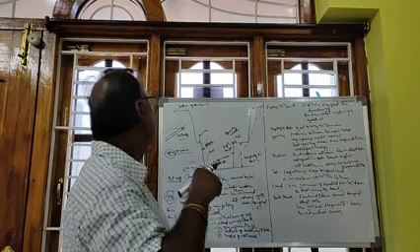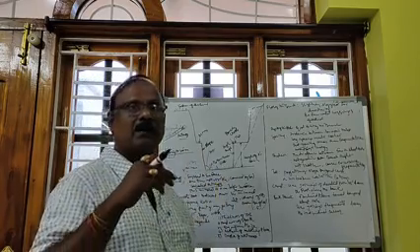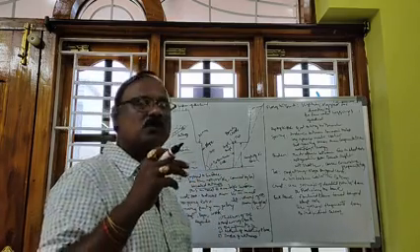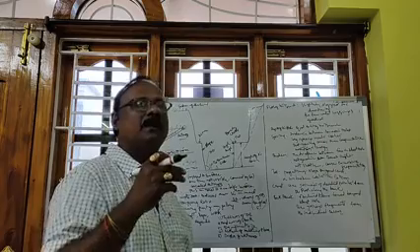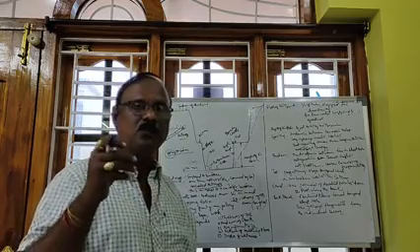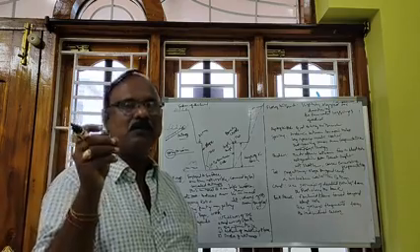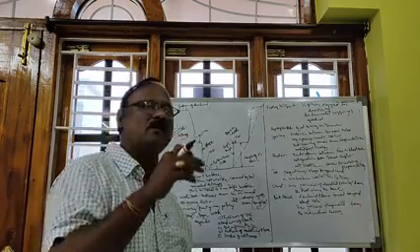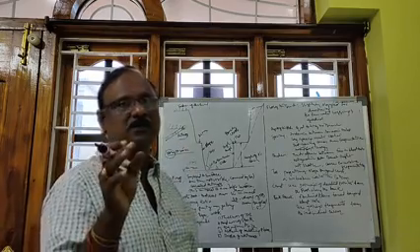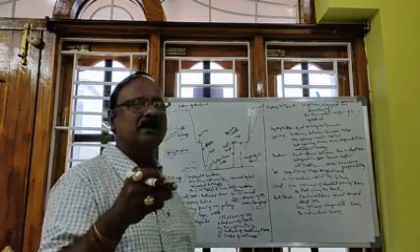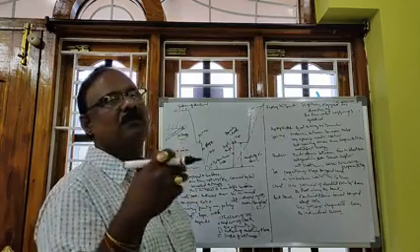Actually, the slope of the bench should not be more than 45 degrees. Why? Because if the slope of the bench is more than 45 degrees, the slope fails and the bench of the OB falls down. A failure occurs, so mining is not possible. So the slope of the bench in the alluvial soil must not be more than 45 degrees.